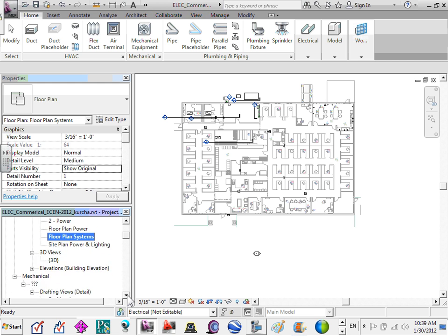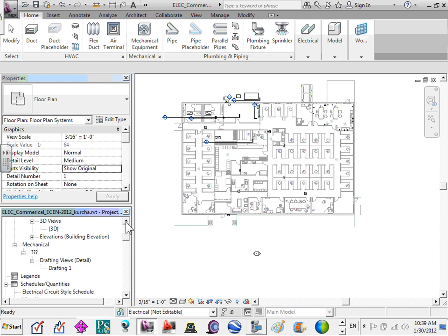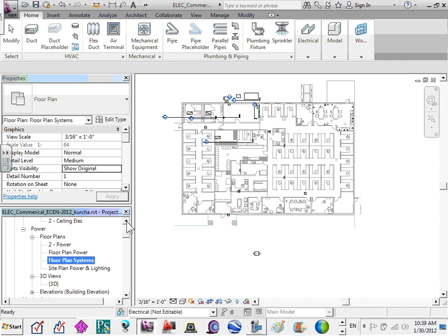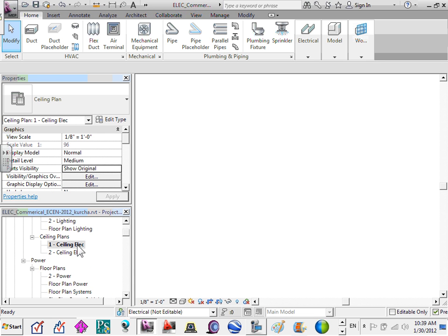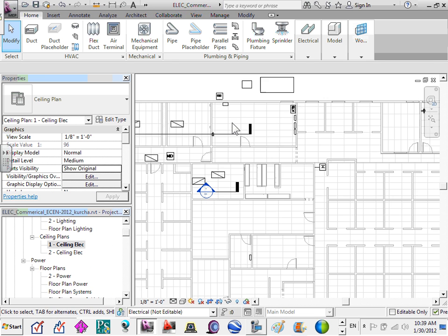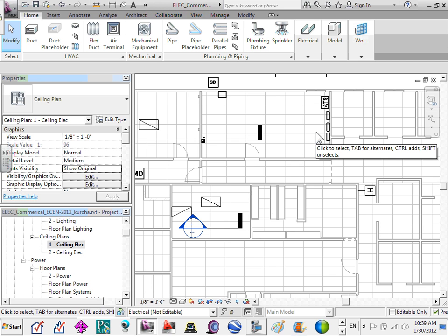Anything in the ceiling, you're going to go back into the ceiling view. Where's my ceiling view? There you go. Now, when you come to the ceiling view, Chris, you're going to have the grid. That's why it's nice to put it in the ceiling view. So all your smoke detector, special smoke detector, and any horn strobe that you decide to put in the ceiling, which is fine with me, you're going to place them here. If you place them here, they will show up also on the floor plan. And then we print from the floor plan. Can I get you guys to say thumbs up? At least we know, Chad, where we are with these ones.